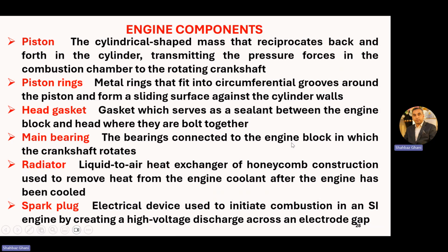Main bearing. The bearing connected to the engine block in which the crankshaft rotates. Crankshaft is connected with your connecting rods, that is your shell bearings, but it has to be connected to the block. So when it is connected to the block, the bearings which connect them are called main bearings. Then we have a radiator. In liquid cooled engines, we have a radiator, a liquid to air heat exchanger of honeycomb construction used to remove heat from the engine coolant after the engine has been cooled.